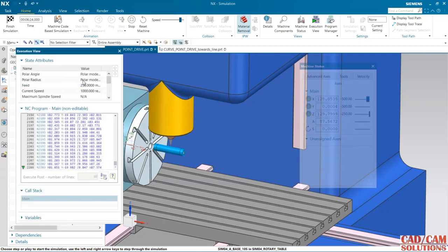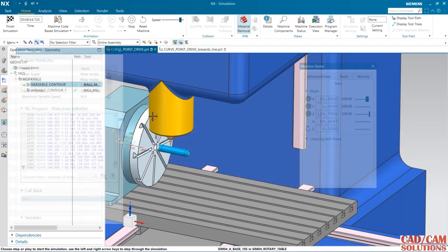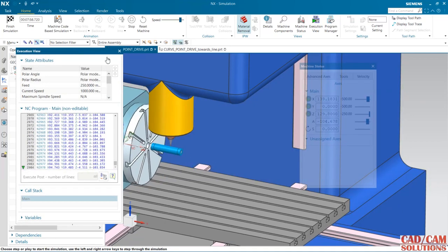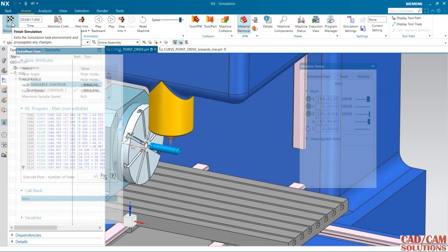My stock is a little bit smaller, so this holder is clashing with the chuck. So no problem. Just increase this blank, and if you want to see the clashing, you need to switch on machine collision. It will show you what other parts are clashing. So hope you understand this operation.